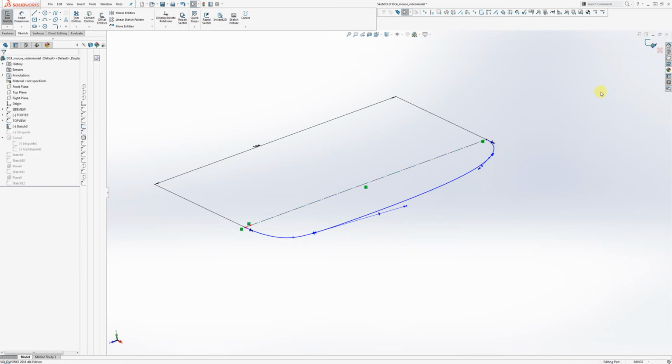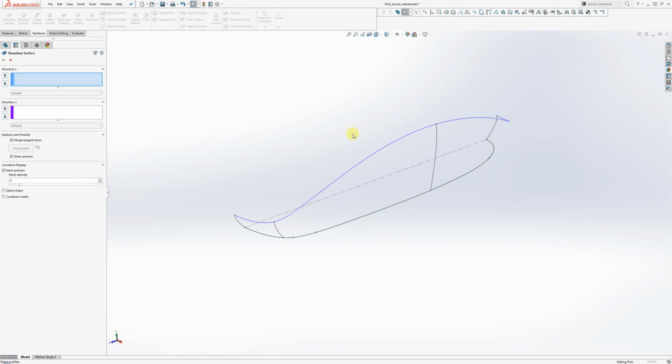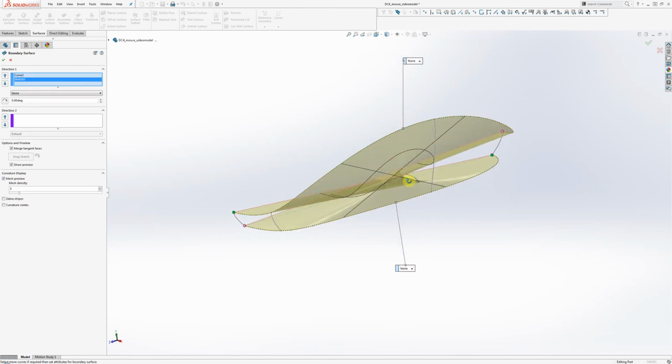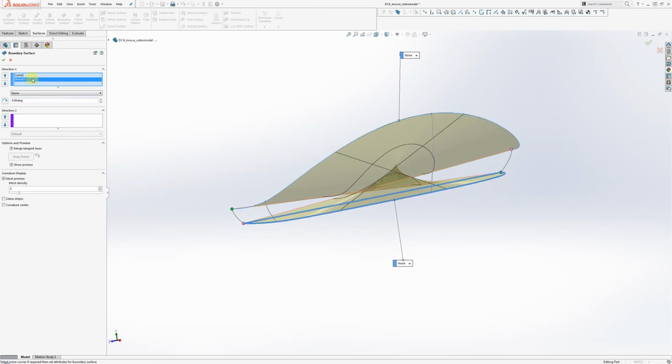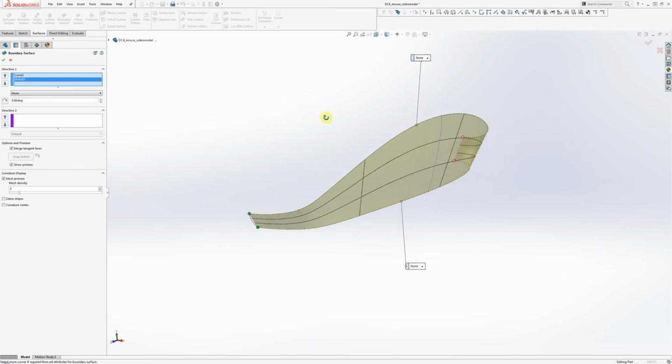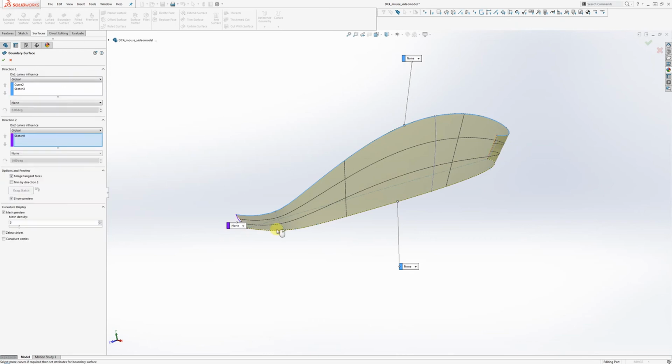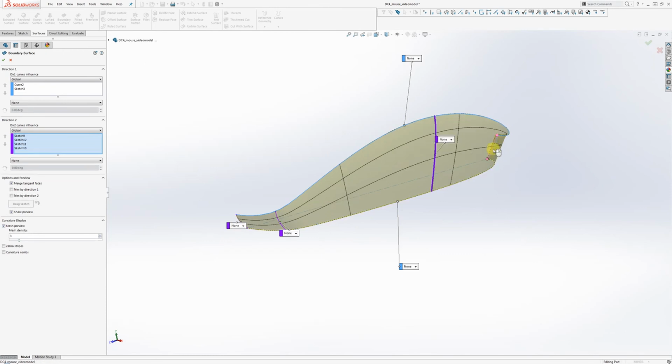So this time, considering I'm having a little bit of a problem here, I'm going to right click on the 3D sketch first, and then go down to the footer curve, the problem curve, another flipped connector. Just flip it back. That's working correctly now. Now I'll use the guide curves as direction 2. I'm going to go 1, 2, 3. It's a 4-step process. Come on. There we go.